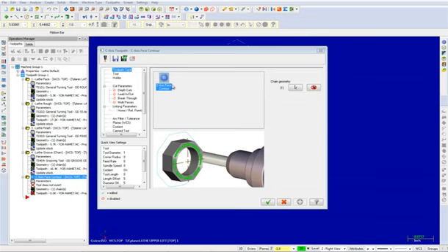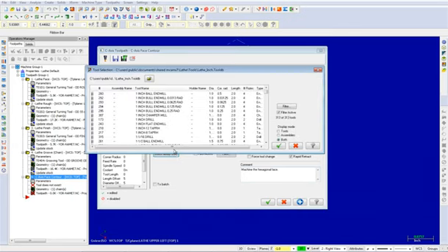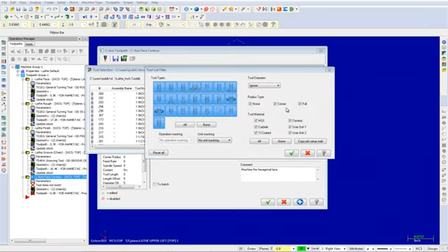From the tree view list, select Tool. Now input a comment as shown below and click the Select Library Tool button. We will select a 3/4 inch flat end mill from the library. To be able to do this, select the Filter button. Filter allows us to find a desired tool easily without having to scroll through the entire library searching for a tool.